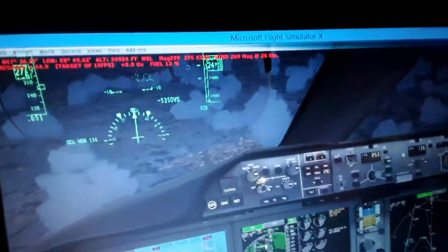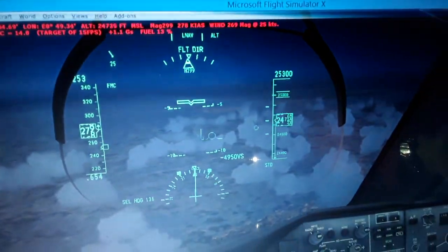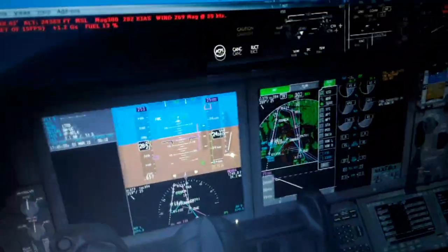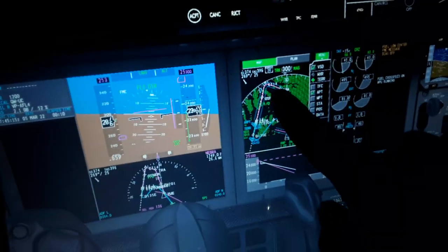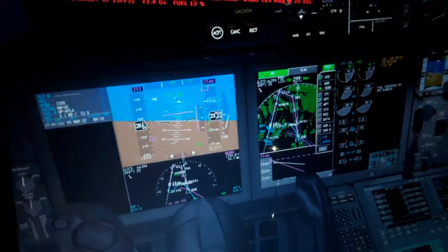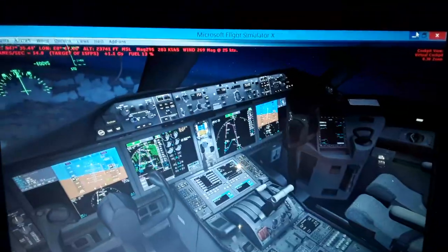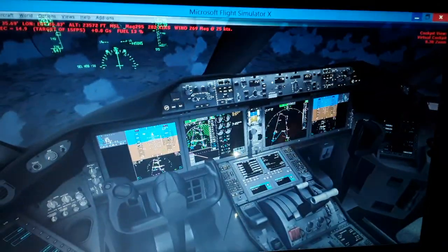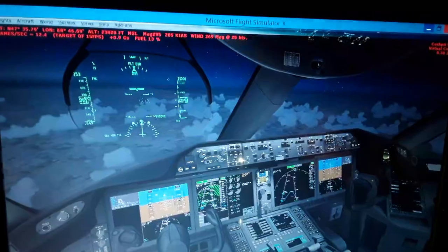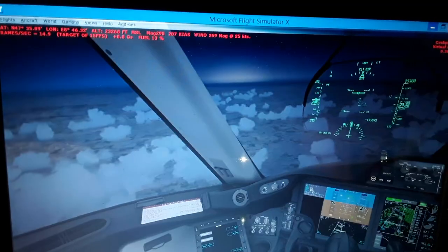So keep descending over here. The airspeed also, the display of the air data, we have it, and we have 6 more minutes. We need to align with the flight plan again, cross through these waypoints and approach and landing. So now we're going for approach as we are descending. Can use a little bit more airspeed like this.